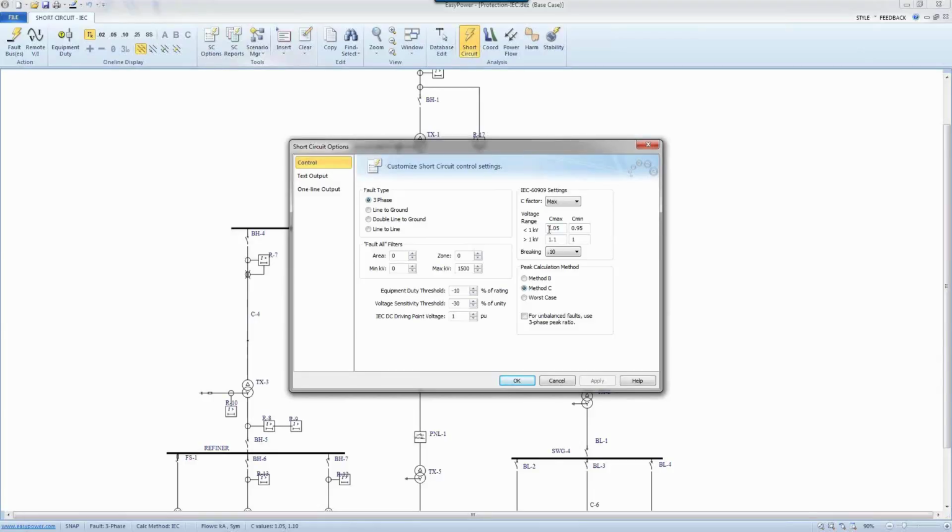Number two, as we discussed, impacting the impedance. Increasing voltage would mean we have to try to minimize the impedance, and the impact on the K factors is something which is already implemented, and those are formulas that EasyPower follows. If any K factor has a C value in it, once the C value changes, those K factors change, and they are going to change and impact, let's say, the transformer impedances. Some other K values that we define and use in, let's say, method B and method C, and all those details, are already implemented.